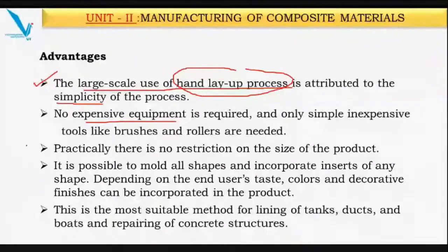Practically there is no restriction on the size of the product. Large ships or boats are manufactured using the hand layup process or spray layup. What is spray layup? That I will discuss in the next slide. It is possible to mold all shapes and incorporate inserts of any shape in that. Depending on the end user's taste, color and decorative finishes can be incorporated. So shapes means you can get any shape.